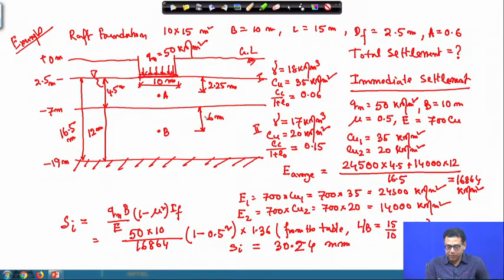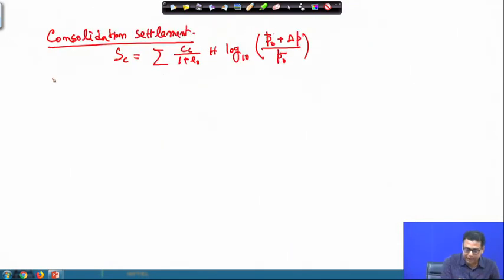Now, I will calculate at point A and point B the P0 bar, the effective overburden pressure. Remember that here only one unit weight is given, so we will use it both as saturated, below the water table, and above the water table. In some cases you may find two unit weights given, one for the saturated soil and one for the soil above the water table.